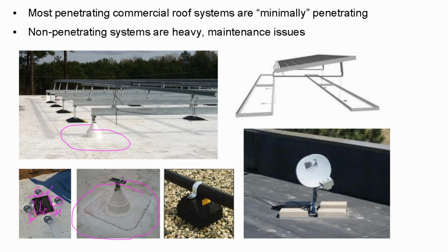And then you have a flash pad that goes over the attachment, and then it just gets melted onto the TPO roof with kind of a souped up hair dryer. So they call it welding. You're not taking a big butane flame and torching it. You're kind of melting the flash pad onto the TPO roof. Something that a commercial roofer does all the time for flashing everything else on a TPO roof.